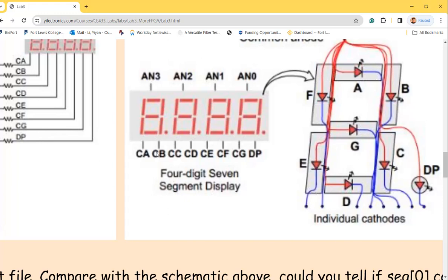Okay. So do you need these pins to be low or high to turn on the LED? Low. That's right. So now here's a question. I have 4 units. Each unit takes 8 pins. So for 4 units, how many pins do we need? 4 times 8, 32. Do we have 32 pins? Do you want to use 32 pins on my controller? It's occupying a lot of pin resources on the microcontroller or FPGA. You want to reuse it? No, you want to reuse it.